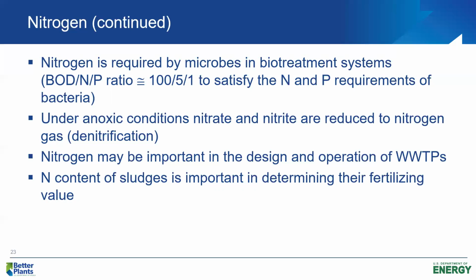So again, when we design an activated sludge process, we need to be aware of the nitrogen content because we will need to look at the possibility of nitrification occurring. And if we have a total nitrogen limit, we'll probably want to design the plant for biological nitrogen removal and include an anoxic reactor to achieve it.